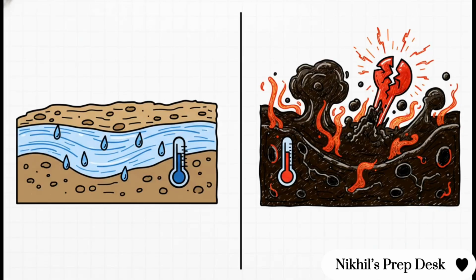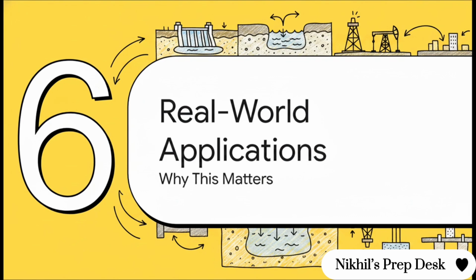Furthermore, Darcy's hydraulic conductivity assumes the fluid's viscosity remains constant. This works great for standard groundwater streams where temperatures barely change across an aquifer, but it brilliantly illustrates why the equation needs heavy modifications if you're dealing with, say, hot oil pushing through deep reservoir rocks. If the temperature fluctuates wildly, the viscosity changes dramatically, and you simply can't apply the standard Darcy equation without making some absolutely crucial adjustments.